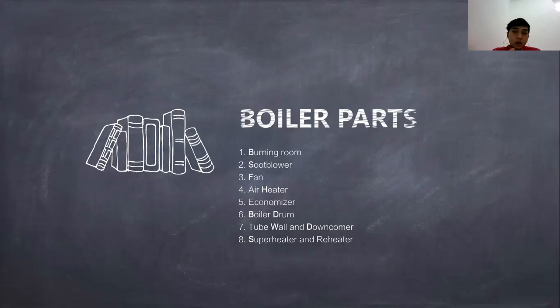Four, air heater. The air heater is installed with plate type elements that work to take heat from the flue gas and then transfer it to the combustion air by a convection heat transfer mechanism.